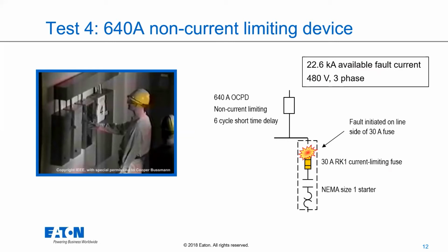Or maybe a feeder in a large piece of switchgear, but it would be one of those bigger low voltage power breakers, the one that had intentional time delay, not the 30 cycle time delay that some of them have. The 6-cycle one winds up being somewhere sort of in the middle of your power distribution system for coordination purposes.